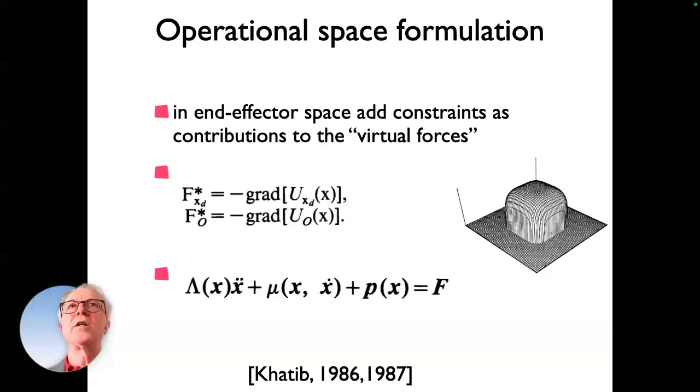That is, you're not just computing purely abstract kinematic planning, but you're also taking into account what that means for the arm, the kind of interaction torques that arise and so on. And so all the physical terms would be exposed to the potential field. So the solution of that equation would already be your control signal.